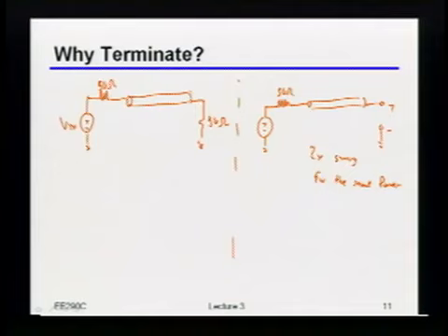Okay, so sounds kind of attractive. Turns out, again, actually most of the time people don't really use this. Not because it's impossible to get it to work, but only because you have to worry about a lot more stuff now, right? You have to worry a lot more about, well, okay, if it's not terminated, then what's really going to happen when I put this into a backplane? How likely is it that I'm going to hit this thing and then reflect back and come back again and so on and so forth?